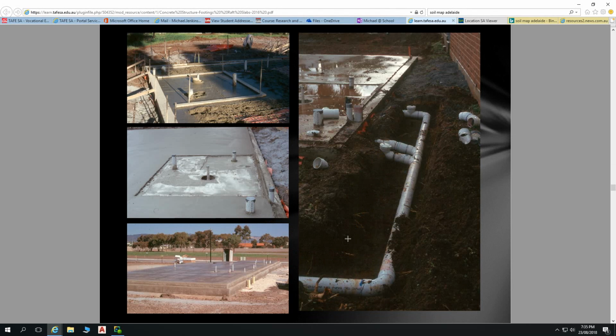We have a set down for a bathroom because we want to ensure that if something happens with water, that water will not flow out anywhere into the rest of the building, but it will go down into the floor trap. It's not always possible to have a floor trap. In some houses with a suspended timber floor, suspended steel floor, etc., you do just platform flooring straight over the top of that. You don't have a floor trap because you can't provide any slope to that floor trap.